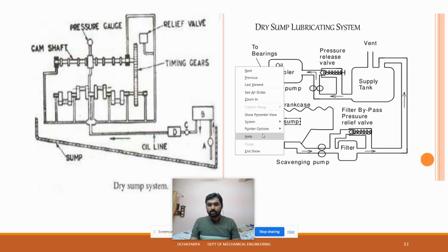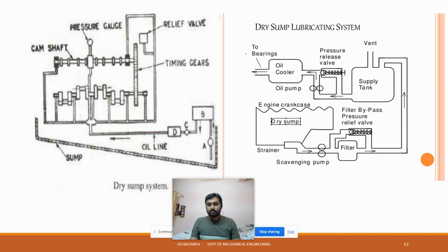So you can see many types of new components. There is an oil cooler and a pressure relieving valve. You can see that some thermostats will also be seen, which can detect higher temperatures. When it crosses that point, the sensor will be used to operate the pressure relief valve. Here also you can see there is a vent. So if it is getting fumes due to higher temperature, you will get a signal so that you can stop the engine and check the particular oil section.